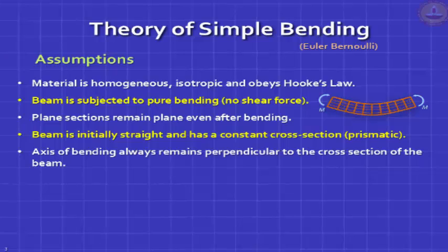It is because of this that under pure bending the deformed shape is a segment of a circle, and you can talk of a curvature and a radius of curvature. All the normal lines will converge to one point and you can draw a circle to any of the layers.